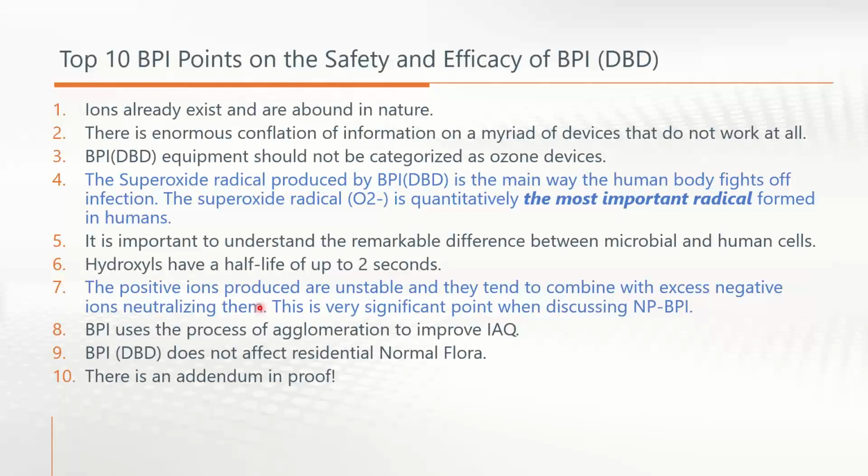And they're not the same ion, the O2 negative. They're an O2 double negative, but when they're going out, they're hitting each other and getting absorbed. So they have to overproduce that ion just to get it out into the space if there's a long ductwork system. And again, that ion that they're producing doesn't have the same ability to kill bacteria and viruses.